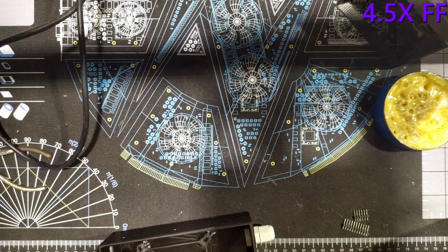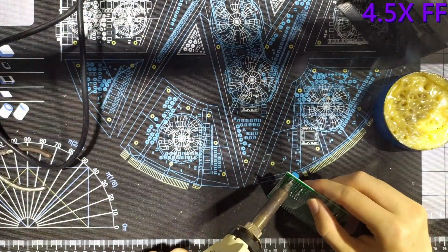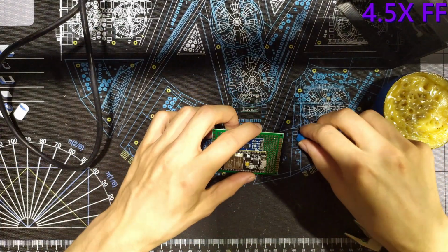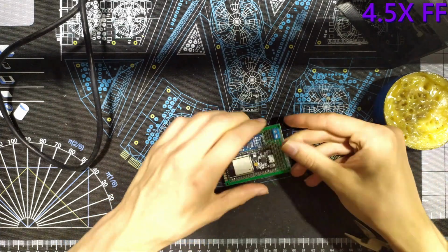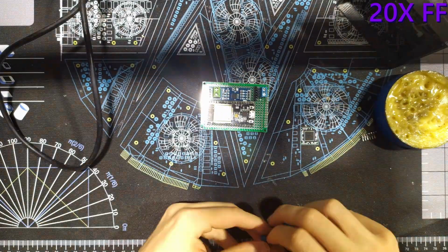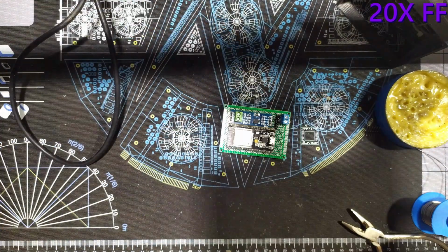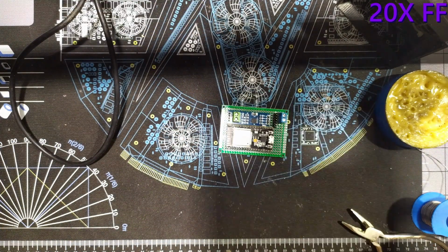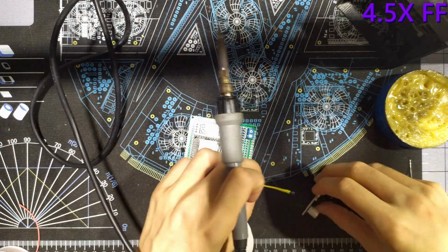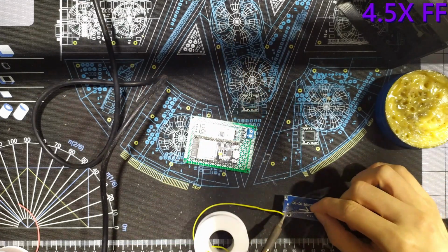I then wasted a lot of time figuring out how to mount the connectors I needed for the display and some LEDs, and decided to slightly change the location of the screw terminal. After that, I could place the pin header for the displays behind it. The next thing I did was to solder wires to the DC to DC converter so I could hook it up to the main PCB.